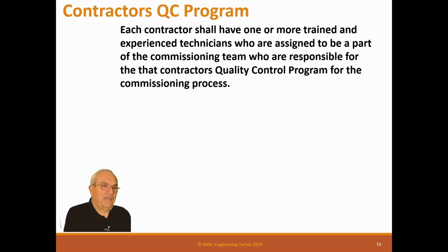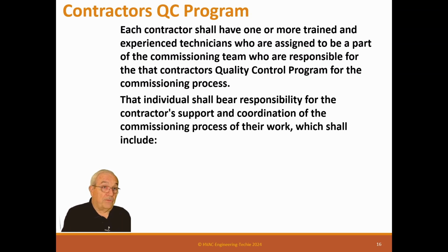So you want the contractor to assign one senior level technician that understands everything about his craft and can answer the questions and help you coordinate the commissioning of his craft. That's really important. If you don't do that, just anybody can wander in from that contractor, and say, yeah, I'm here for the contractor. And he may not have any really good line of communication for that contractor or no authority for that contractor. So you need to have them tell you who that person is.